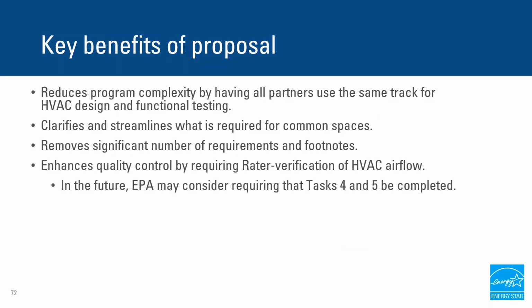We think this has a lot of benefits to reduce complexity and have everybody using the same track and align all the requirements across the systems and the spaces, and streamline what's required for common spaces, as well as remove a significant number of requirements and footnotes, and overall enhance the quality control by requiring rater verification of the HVAC flow for most system types.